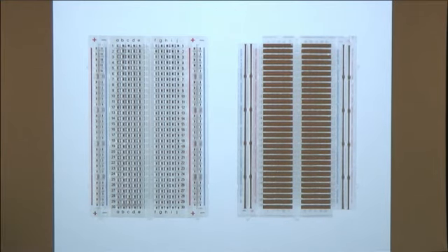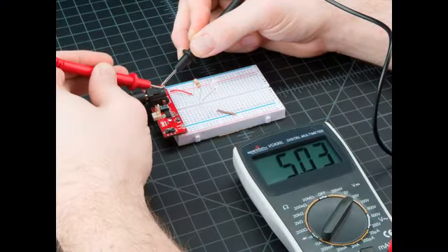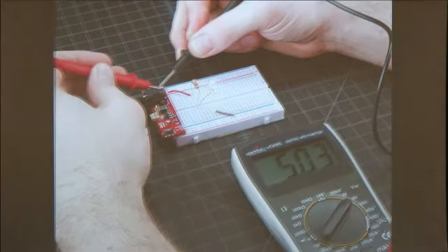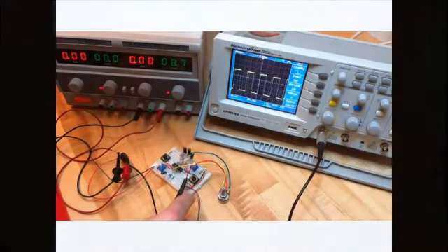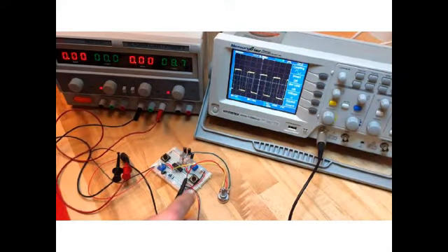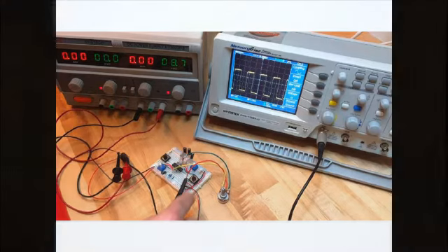Now, if you want to debug your breadboarded circuit today, the usual way you do that is by coming up with a hypothesis of what might be wrong, then breaking out your measurement tool, like a multimeter or an oscilloscope, and then doing a point-wise measurement to check if, according to your hypothesis, I would expect measurement X. Do I see that or not? And you can do that just on voltages, or instantaneously, or over time with an oscilloscope.